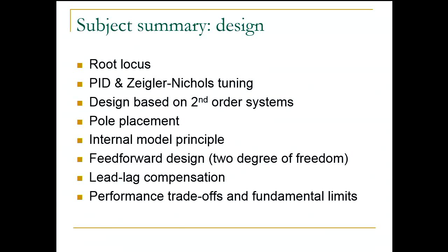And if all other poles are further to the left in the complex plane, they will be faster, and their contribution to the response would quickly die out. So this dominant pole design can guide us to use all the things we learned about design for second-order systems and apply it to higher-order systems, right?